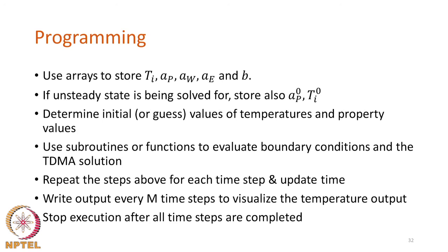In case you are introducing temperature variation of properties, then because temperature is also varying at each location, you may have to again use arrays to store the property values, and you have to update the properties at every time step as and when the temperatures are changing.